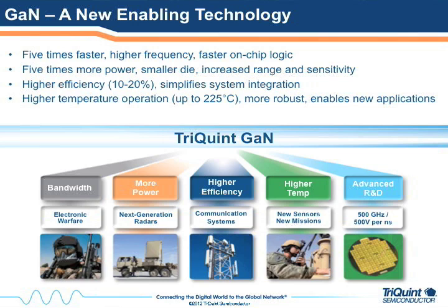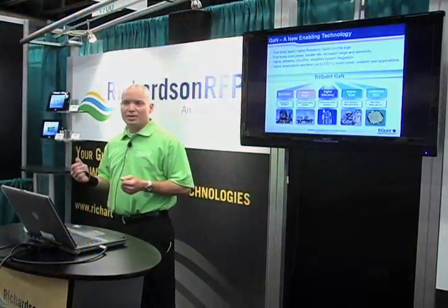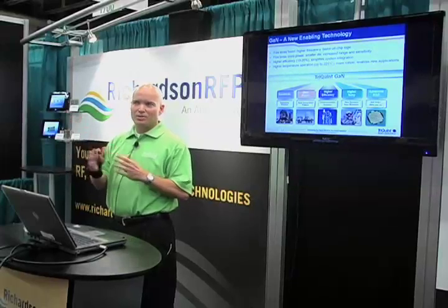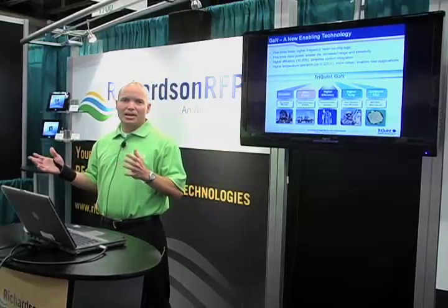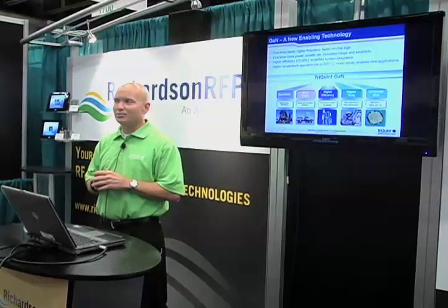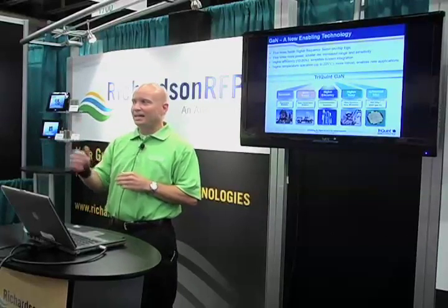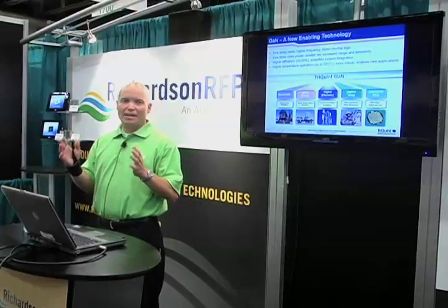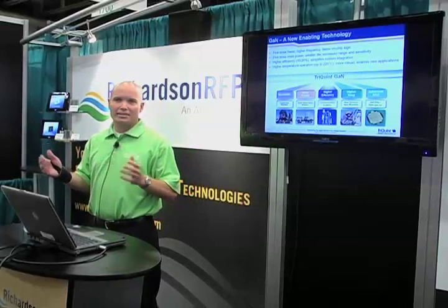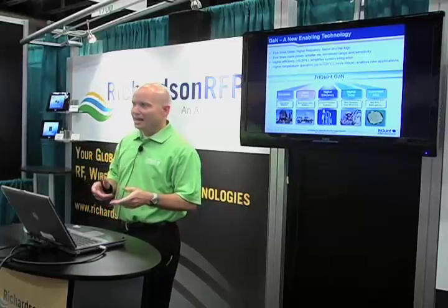It brings to the table higher efficiencies. GaN really separates itself from gallium arsenide in terms of efficiency when you go higher in frequency as well as broader band. What we're achieving broadband with GaN is twice as efficient as what we achieved in gallium arsenide. Same thing as you go into Ku band, even to Ka band, the efficiency levels that you can achieve with GaN are twice that, if not more, than what we were able to achieve in gallium arsenide.